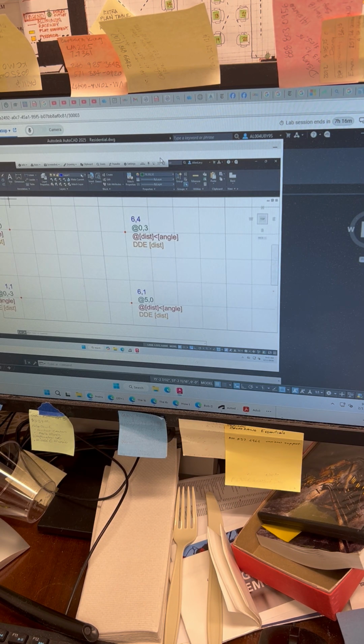All right, so same as before, I'm going to use a different color. And I'm going to start the line command at the absolute coordinate of 1, 1. All right, now as I mentioned here, you can see it's my dynamic input, but I'm still going to use the old syntax to get to this. At, and there's the at sign, 5 units. See this? At 5 units, and here I'm going to put in the angle symbol here at an angle of 0 degrees. This is exactly to the east.